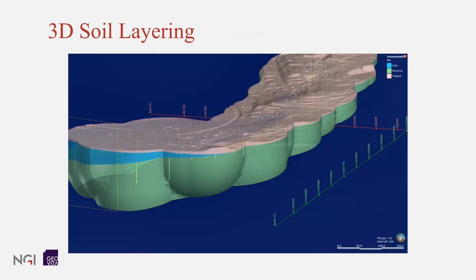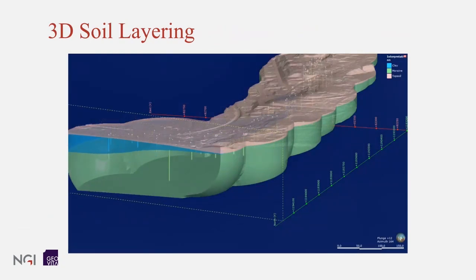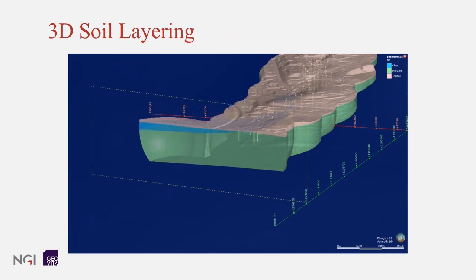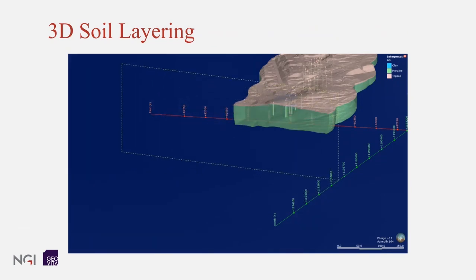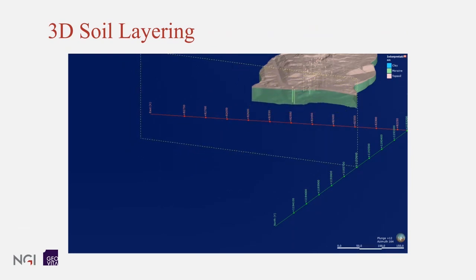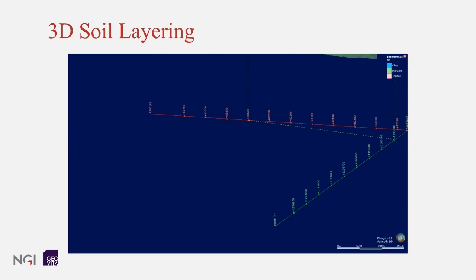When you have created the bedrock and terrain surface, you put them as boundaries, and with a few clicks, make the software interpolate between the boreholes. I have also added a distance boundary to the boreholes of 100 meters.